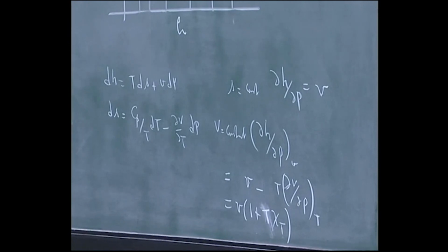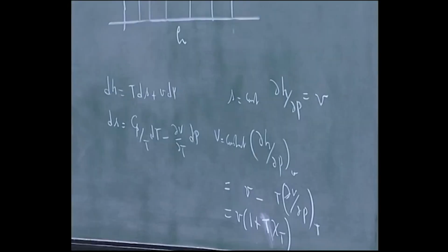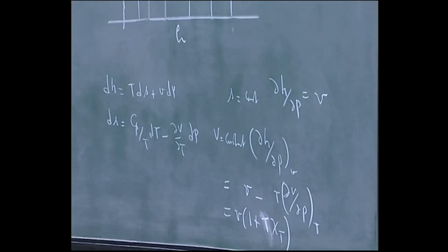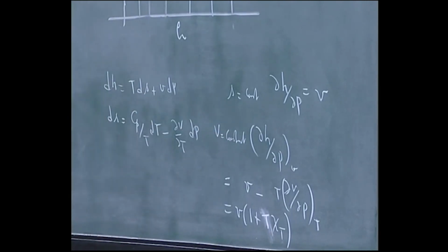Actually it would have been nicer if people had defined that as the coefficient, and you do not have to worry about dimensions, but in practice chi of T is reported in degree K minus 1. So you multiply by T, and so most tables will give you degree K minus 1. So first of all, the isentropic lines, when V is equal to constant, so let me write the slope of these lines.